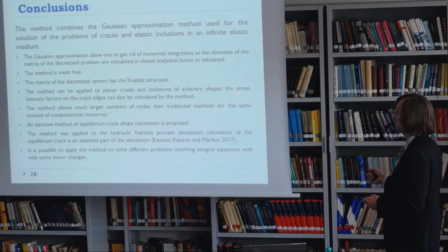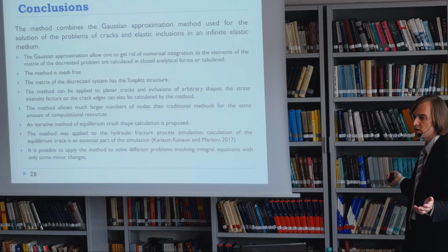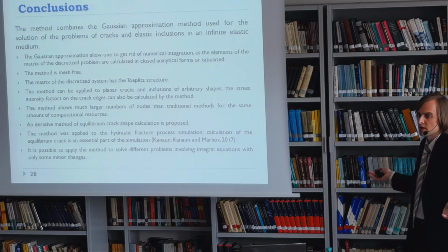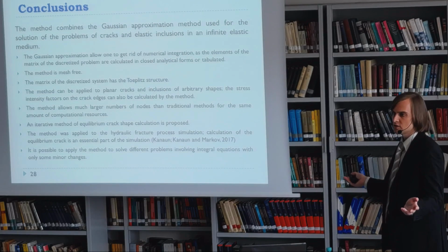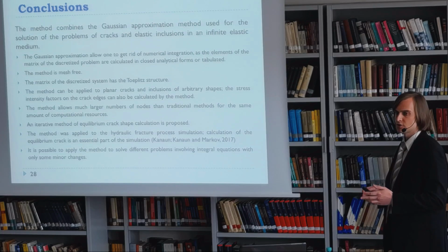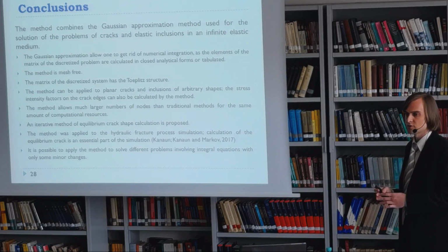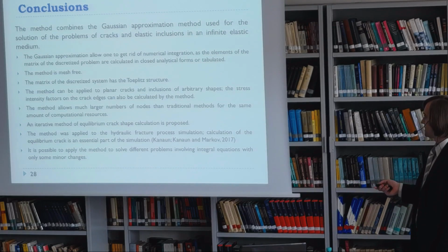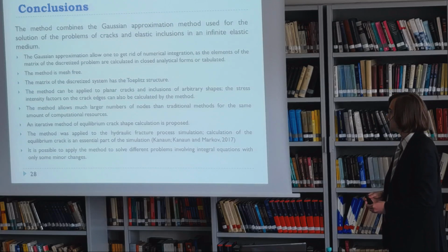This method might be applied to planar cracks and inclusions of arbitrary shapes, so it doesn't matter. The shape is basically defined just by some index function, and that's it. So we don't need to draw it somewhere in CAD and import the geometry. This is actually not necessary. The cracks and inclusions are simulated by just an index function. The stress intensity factors are calculated by this method in a simple form. This method would allow us a much larger number of nodes because of the triplet structure.